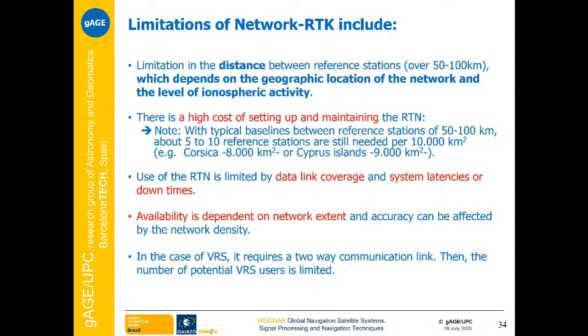But still, if we have to cover a continent or a wide area, even having these large baselines, we need to deploy a wide reference station network. For instance, in this case, we need about 5 to 10 reference stations to cover 10,000 square kilometers. This is Corsica or Cyprus Island, on one hand.